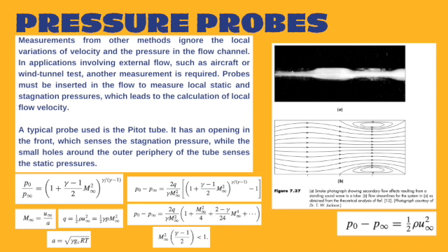This relation may be simplified to the sixth equation, where the Mach number for stream velocity can be stated with the seventh equation, which is an assumption. For a very small Mach number, the equation reduces to the familiar incompressible flow formula, which is the eighth equation stated in this slide.